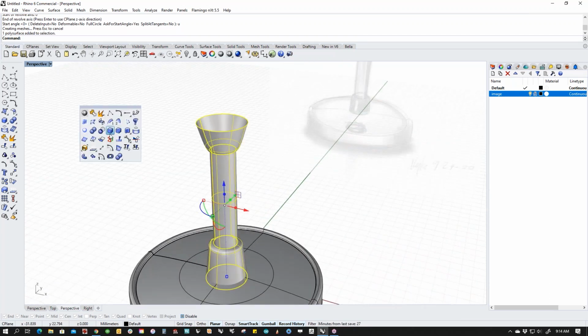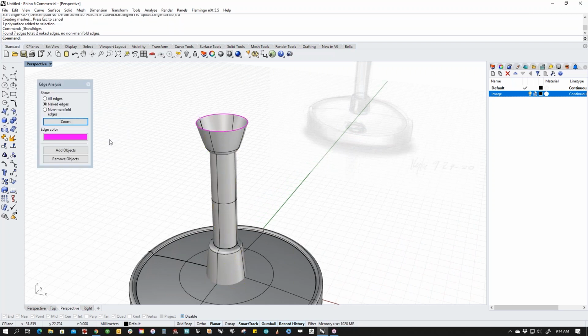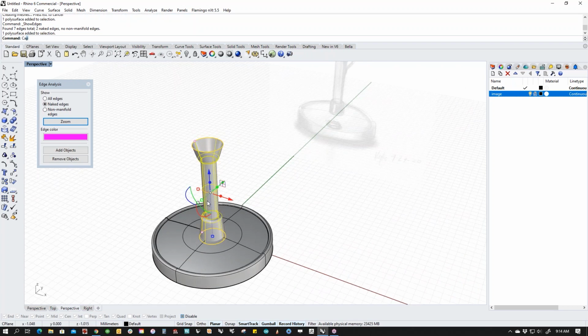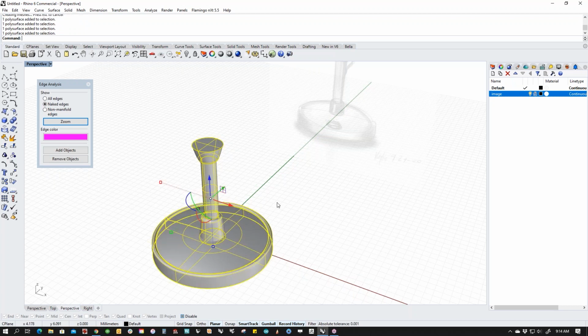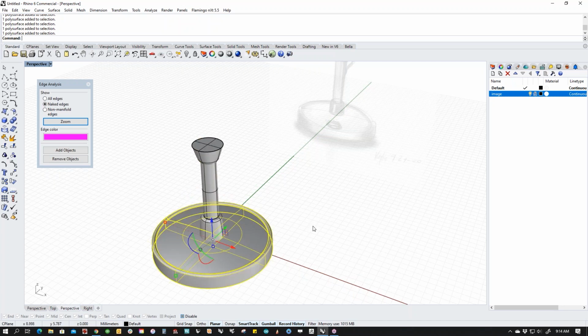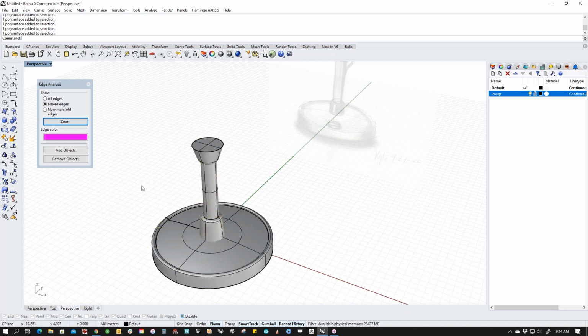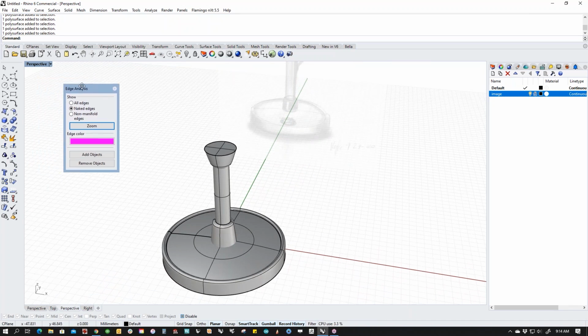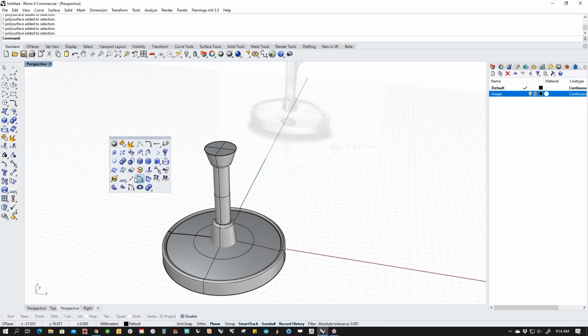Now this thing is open, right? If I say show edges and I've got that in my pop-up, it's open, right? So all I have to do is cap it, and now this is a closed chunk and that's a closed chunk, and I can either Boolean these together, do a difference, or I could print this part and print this part, and I know that it's good to go, right? So that's one of the reasons that I like to continuously work in chunks. And sometimes I'll even just leave this open, but because I have it in my pop-up, I just refer to it easily.